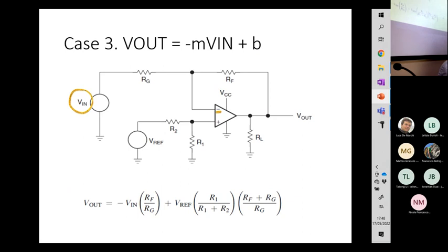You can find these analogies in all the different configurations. So you see the input connected to the negative input here because we want a negative M. Okay, it is always the same mixing between the inverting and non-inverting configuration plus voltage dividing through the series of two resistors.